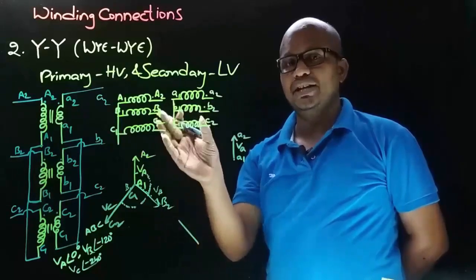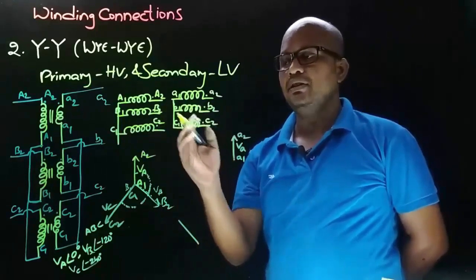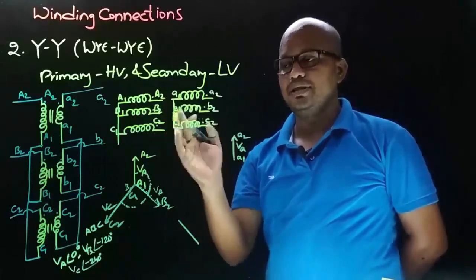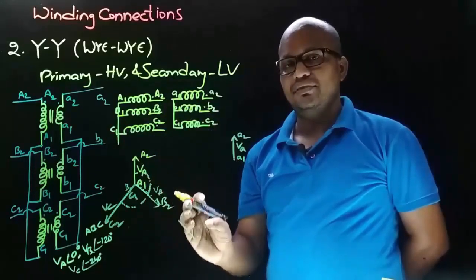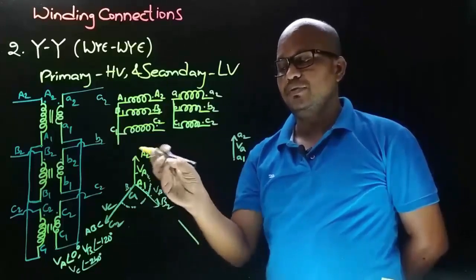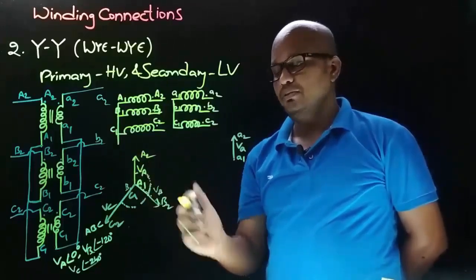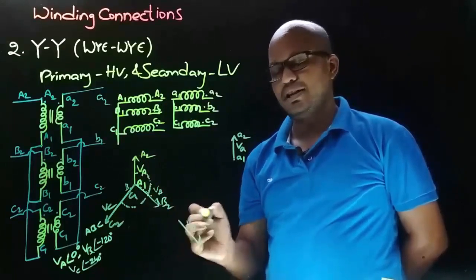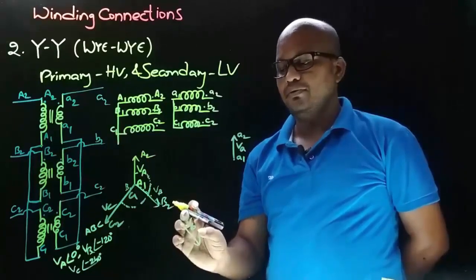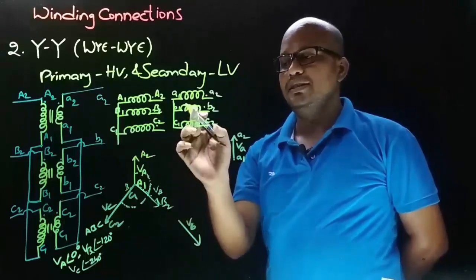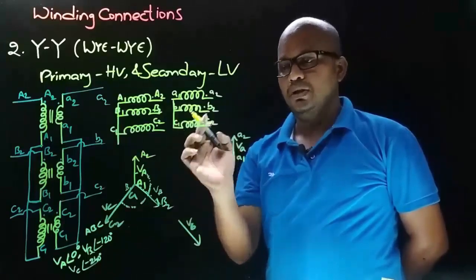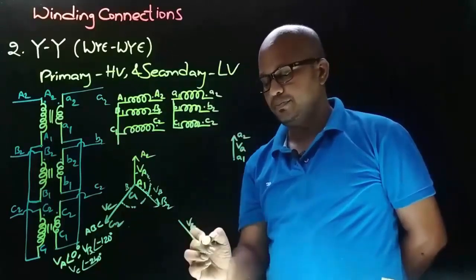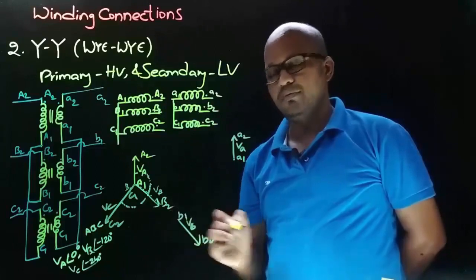So observe the winding connections on primary side and secondary side. On primary side and secondary side we took the connections from dot end terminals, means here the secondary side phasor direction will be same to that of the primary side phasor direction. So VB will be in same direction. And now we need to decide the terminals of VB phasor. So VB is having terminals B1 and B2, and connection is took from B2, means arrow will point towards B2. So this end will be B1.